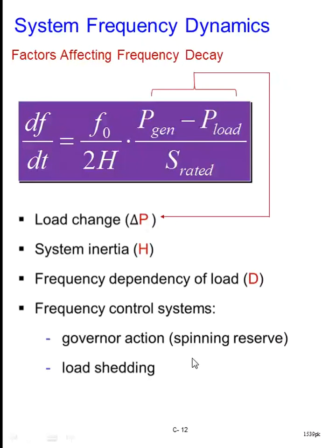The amount of load shed would depend on the frequency deviation, by a certain percent. It is again the regulating policy, and it differs from system to system.